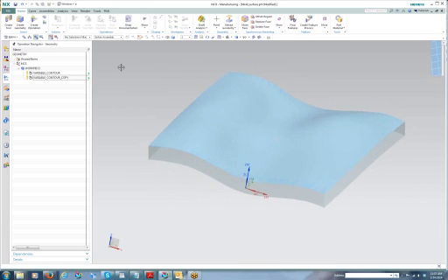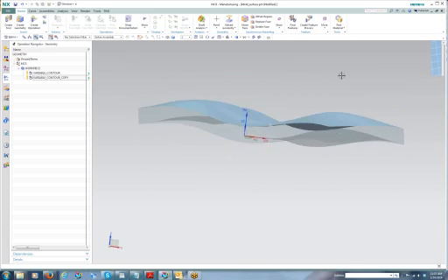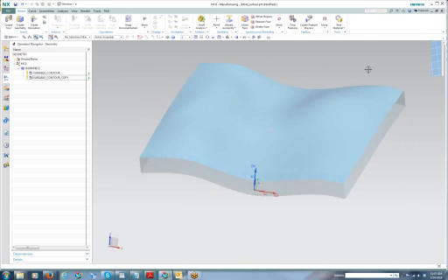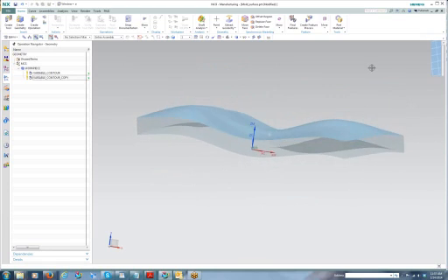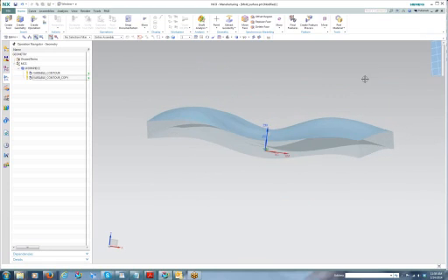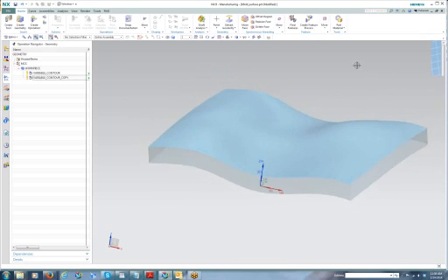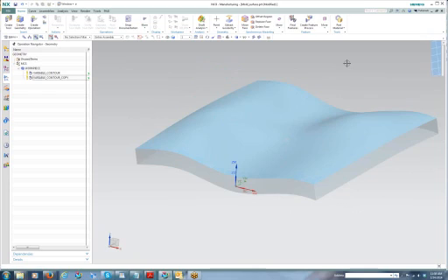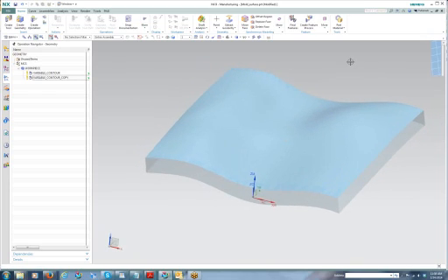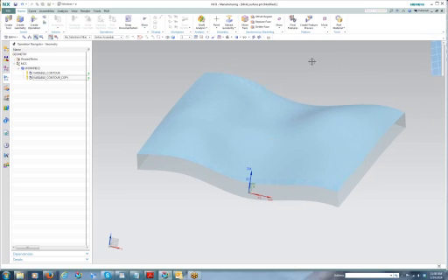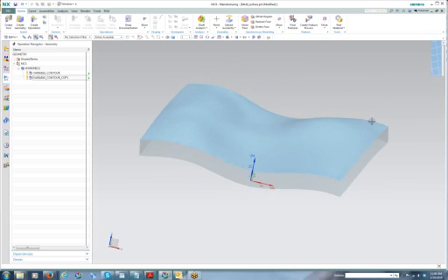In this example, we're simulating a large tool that we're machining as an aerospace mold surface. The tool has been rough formed using either cast or welded together sections, and what that means for us is that the amount of stock that's left anywhere on the tool is variable. However, because it's a large tool, we don't want to be doing a lot of air cutting, so we want to be able to machine only the areas that have extra stock while we're roughing our way down.